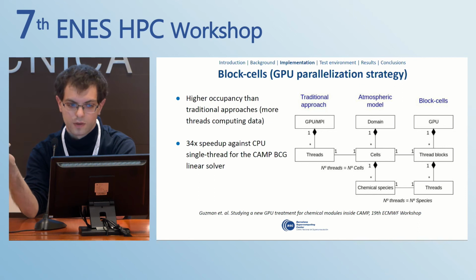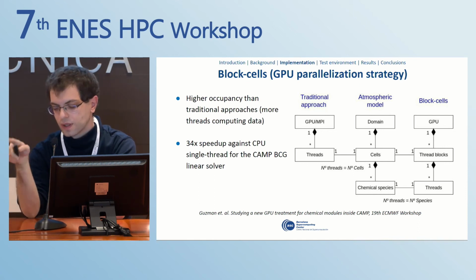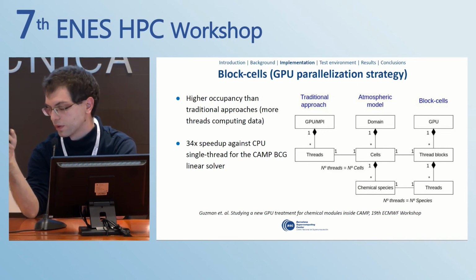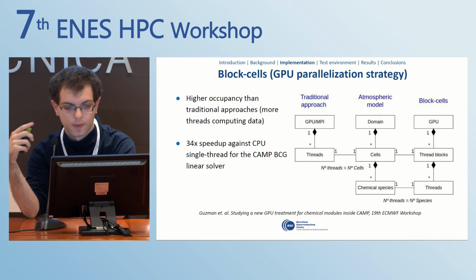This allows a higher occupancy than the traditional approach, so we have more cells computing data. And in the linear solver part, we already tested this strategy, obtaining a 34 times speedup against a single CPU thread, taking into account also the memory data movement and all this part.